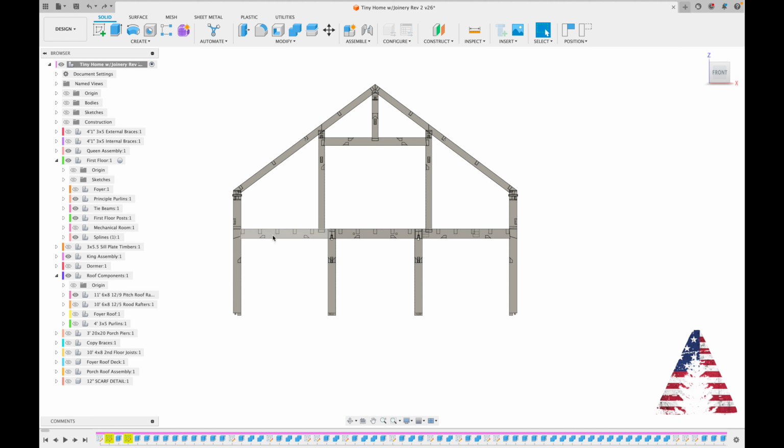So typically when you're building a house with that style, the width in this direction on this plane here becomes the limiting factor, right? Because you might be able to find a 20 or 30 foot long piece of timber that will support this, but that could be as long or as wide as this could ever be, because you really want this to be one piece.